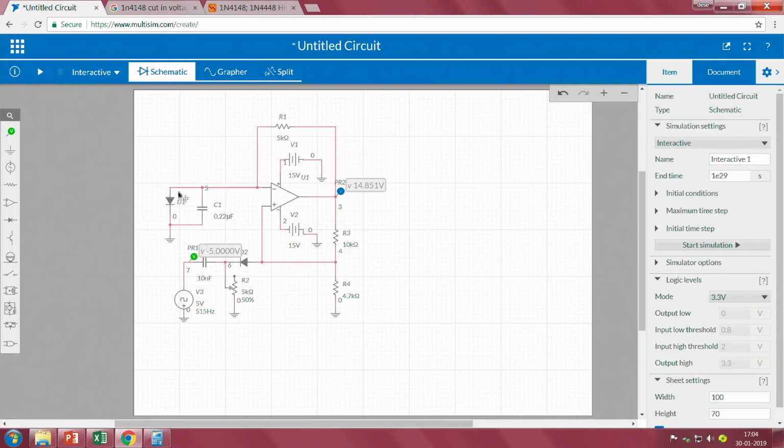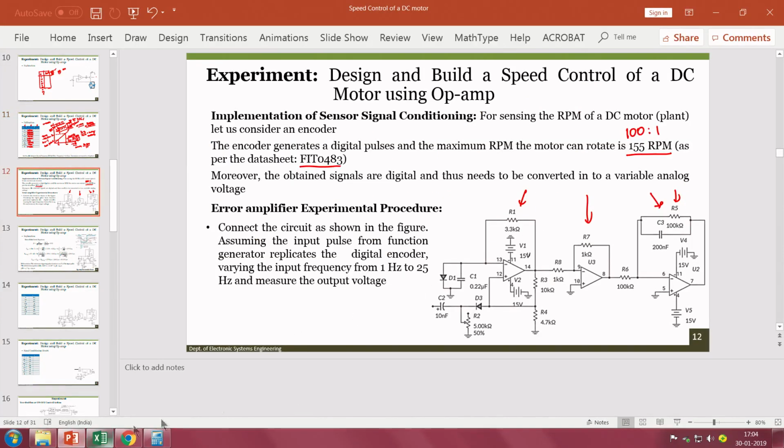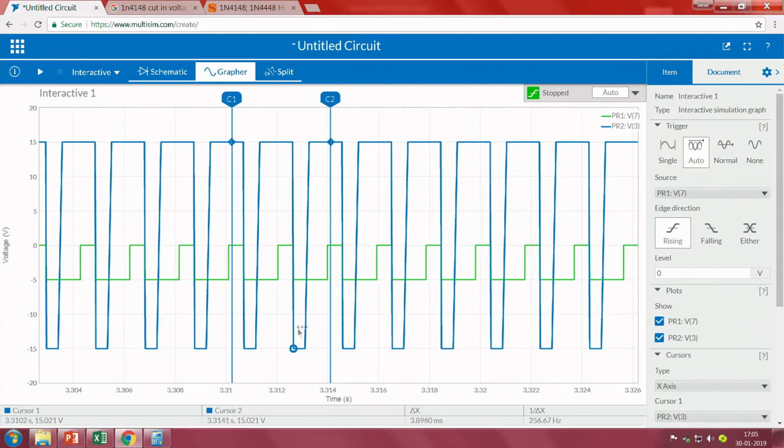Not only that, please be careful when we are giving a signal at the triggering input. Any changes will ultimately affect the output results. So this should always be a negative triggering pulse. Now I hope it is clear why we are doing it. So, the next part: if you observe here, we are getting an on time, the T1 duration, a fixed duration during the negative pulse. This is the unstable state, and this is the stable state. The stable state is positive, but we require it the other way around.